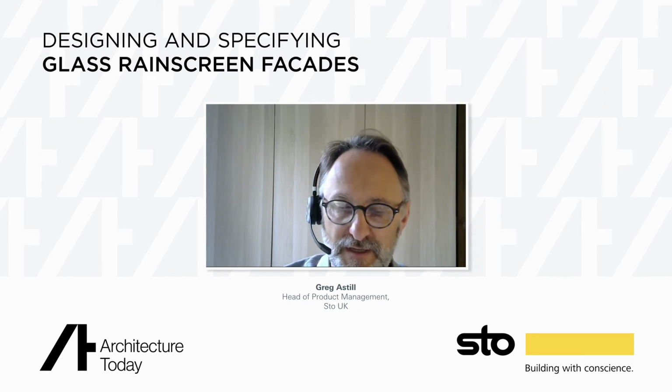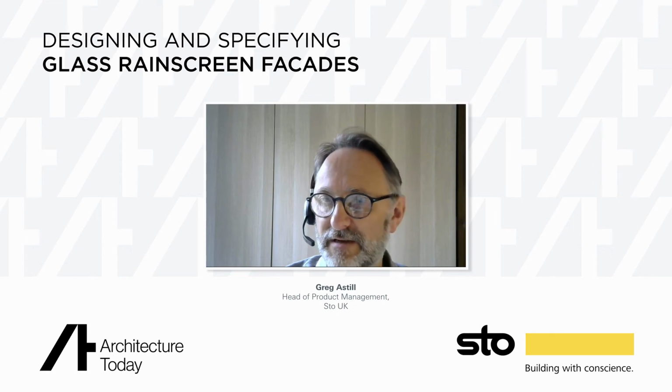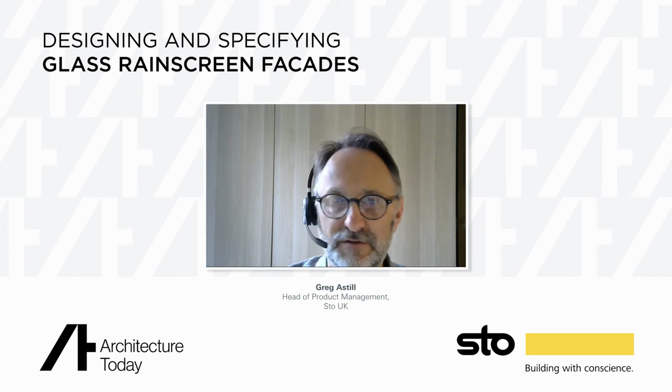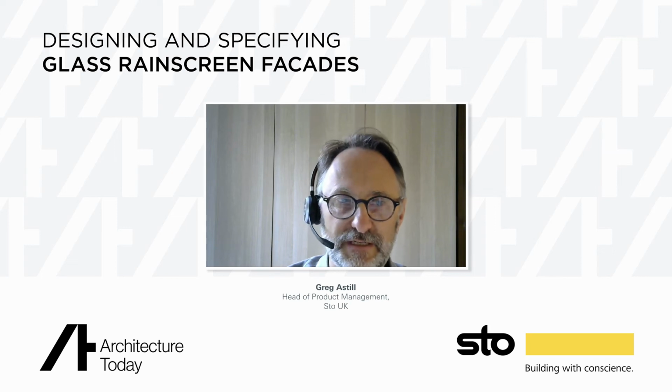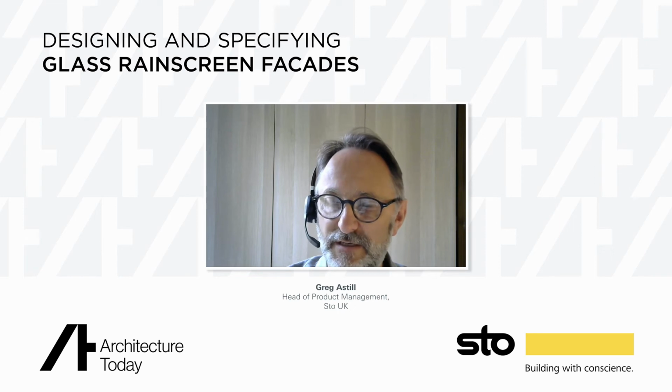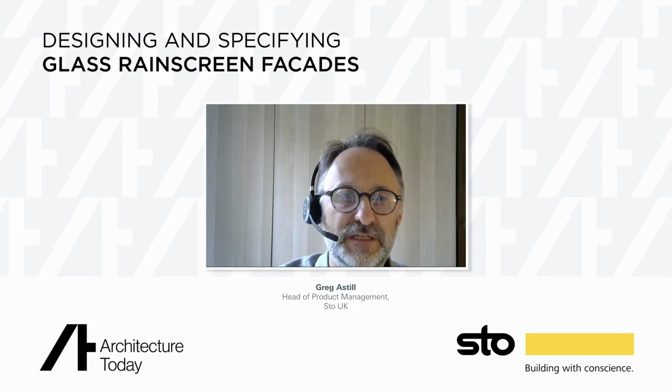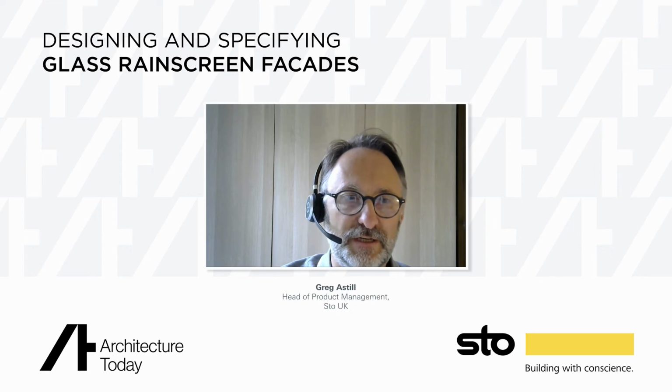But the open state cavity barrier, typically it's an intumescent material on the face of that cavity barrier, which then reacts to heat. So when the heat reaches a certain level on the face of that intumescent material, it starts to expand, it reacts, and closes off the cavity. Typically these open state cavity barriers will be specified for a maximum distance that they can close off for the time that's required.